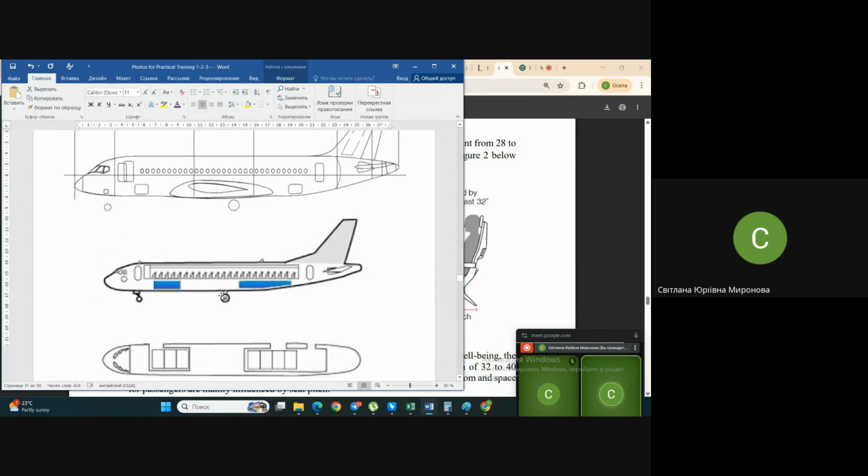Usually it's hidden in the fuselage. And where in the fuselage? You see, somewhere here will be the center wing, and additionally there will be niches for the main legs of landing gear. And all this it's necessary to consider in real designing of the airplane, or at least during the preliminary laying out of this airplane.